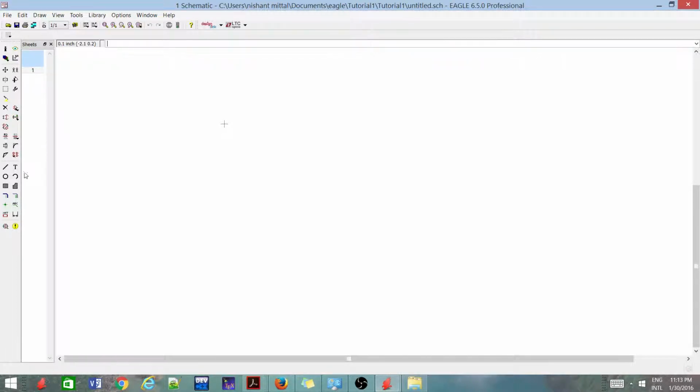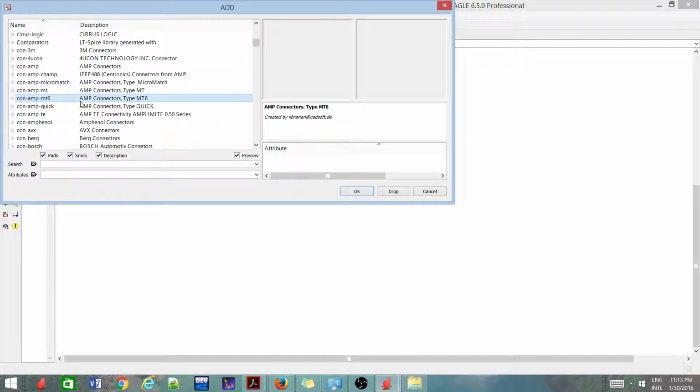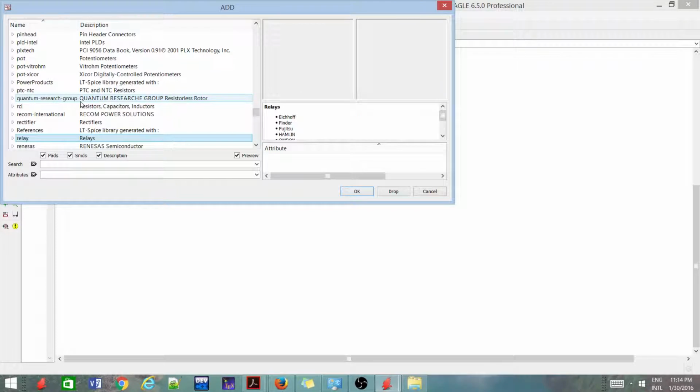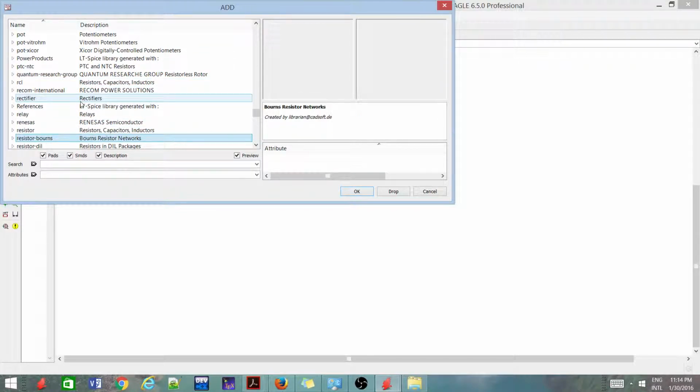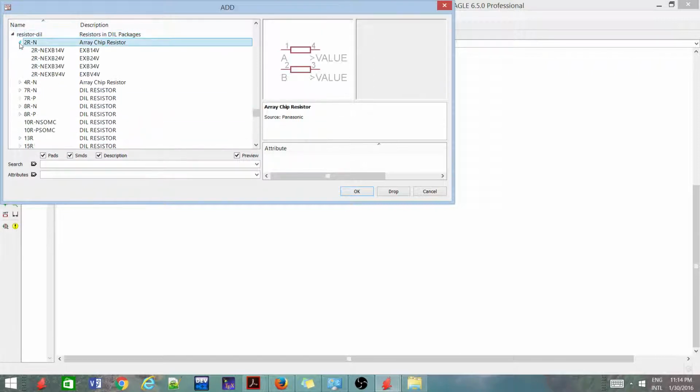Now the second tool is your wires. So these lines act as your wires. Let us make one basic design. Suppose there is a resistor, so you can use your shortcut keys. If I press R, it will automatically go into resistors, or if I quickly write resist, it will enter into resistors. So let us select.